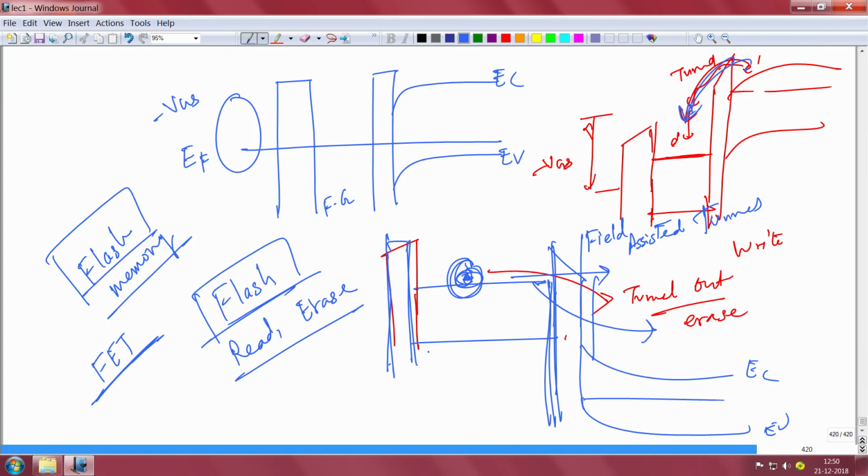So we will end the class today here. We have discussed the final part of RF transistors, the Johnson figure of merit, and also I told you about the power frequency limit that you have and different materials that you can use for superior performance, like indium phosphide and gallium nitride. Then we moved ahead to flash memory and the different kinds of memory technologies. I told you that flash memory is one of the rapidly expanding memory device markets. Silicon MOS structures with a floating gate in between the gate oxide and tunneling oxide enable this. You tunnel the electron in and out through the tunnel oxide, and that's how you read and write the data. It happens in a flash, very quick. That's why it's called flash memory.